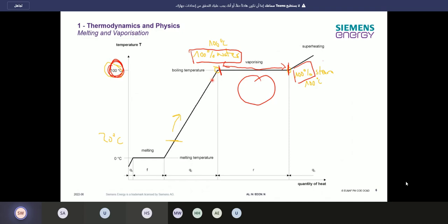So you have there a certain pressure, and then let's say in the preheater you don't want to have evaporation. Or in the economizer, like it's called in the boiler. The economizer should always stay underneath the boiling temperature, because it's not designed for it. An economizer or preheater is designed for water, just from the volume you're bringing through there.